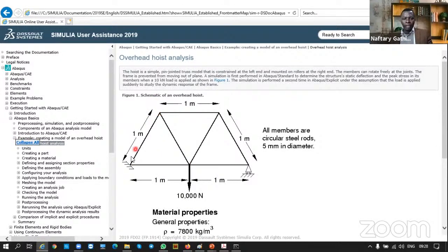You calculate. You see, we have how many elements? It'll be 1, 2, 3, 4, 5, 6, 7. And is it symmetrical? Think about it. If it's symmetrical, you can apply a special boundary condition, and then you can mirror. So this you should be able to handle manually in a very easy manner.